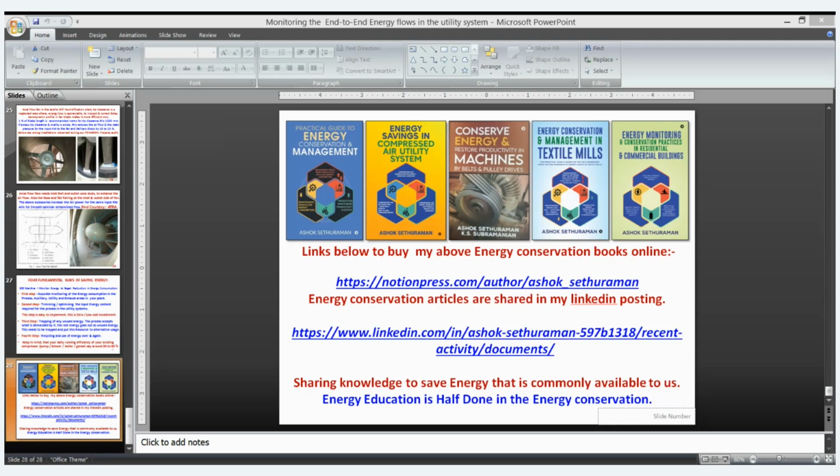See, energy conservation or replacement can happen only when the existing system is already efficient. How to improve upon it further is more important now. So IE5 definitely scores better than IE4 and IE3, but let us see, with IE3 and IE4 with VFD, what is the condition, what is your case study, what are your parameters measured, and then on replacement with IE5, that is with inbuilt VFD, you definitely see the savings, and accordingly you can plan.